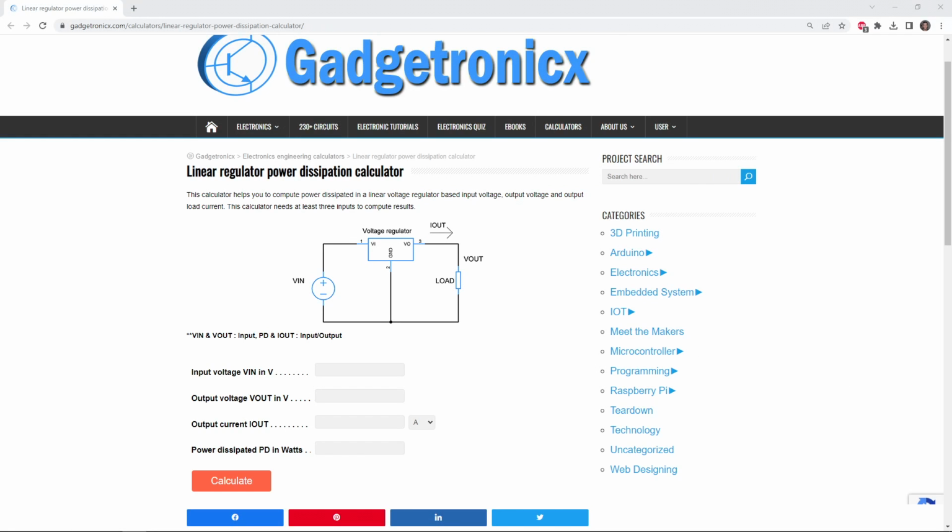It's very simple to calculate the power that is dissipated in a linear or LDO regulator. We simply need to know the input voltage, the output voltage, and the output current. Let's say we are running from a 9 volt supply as our input, so we'll type in 9 for our input voltage, and for our output voltage we want to run, for example, a fairly beefy microcontroller that typically runs at 3.3 volts. If this microcontroller is not doing very much, we could estimate it's in the tens of milliamps and maybe even 100 milliamps at a stretch.